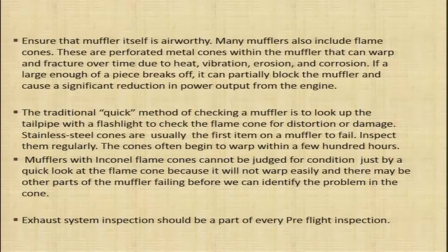So the exhaust system needs to be thoroughly inspected for cracks, for leaks, for corrosion, for vibration and any breakage.